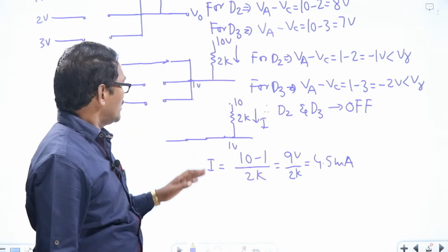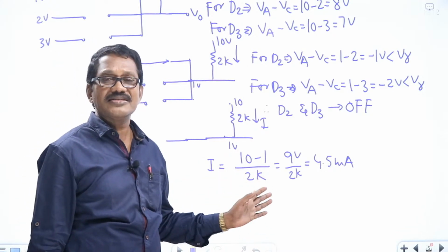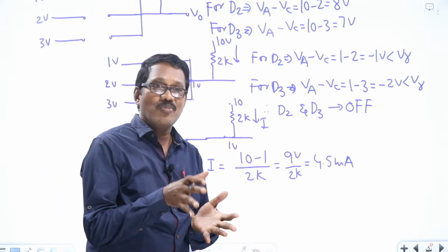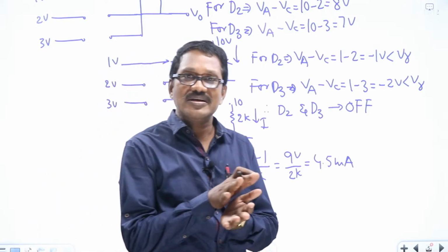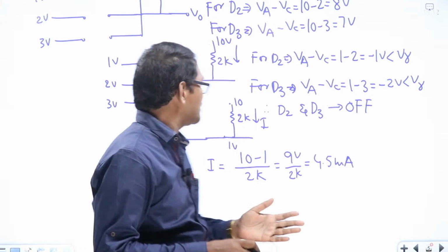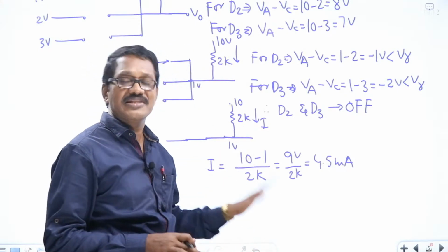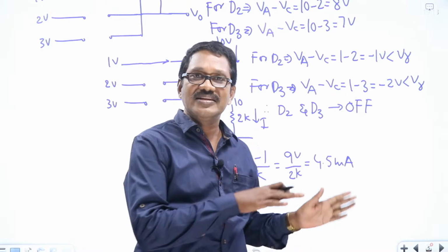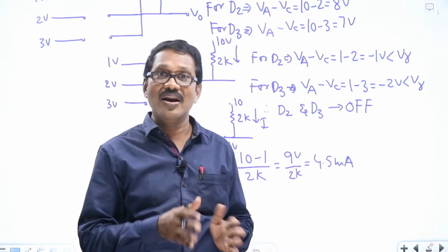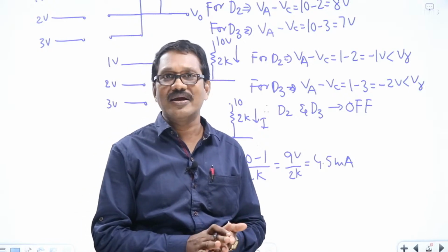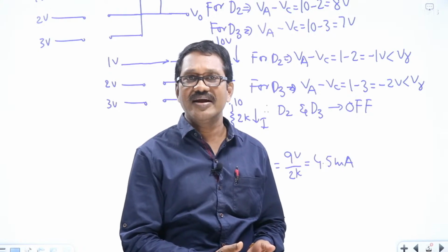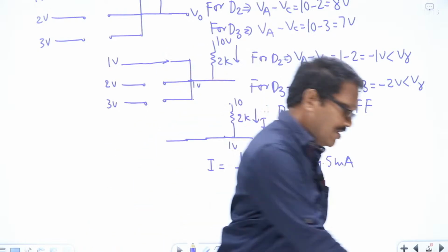Right? So, the very important thing to be noticed in this case is, if multiple voltages point to the same node, that is practically not correct. That is why the short circuit test is not applicable in this case. Whenever you come across this type of problem, you observe whether the short circuit test can be applicable or not. If it is not applicable, then you must go for open circuit test. Have you understood this? So please comment on this.